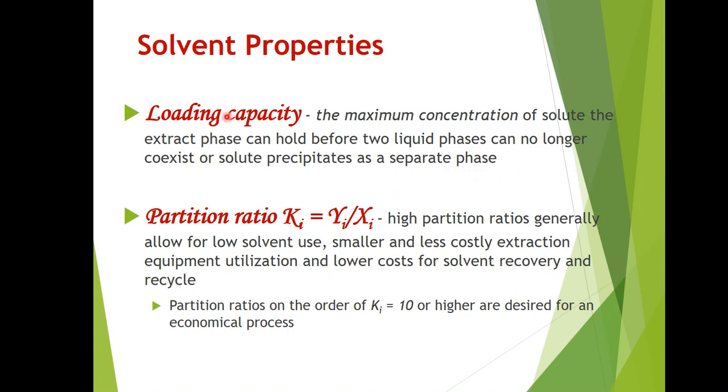So the maximum concentration of the solute in the extract wherein no crystallization happens yet is what we call the loading capacity. If it goes beyond this maximum concentration, your solute will precipitate as a separate phase, and that's already the case of crystallization.